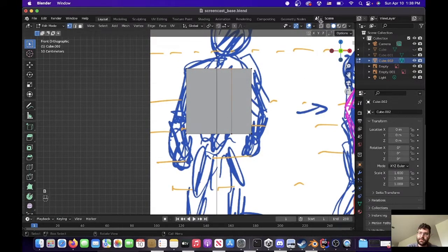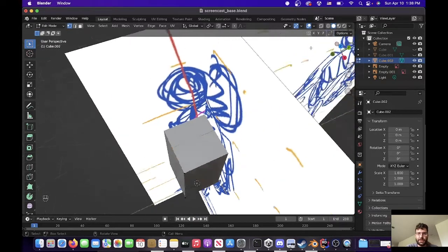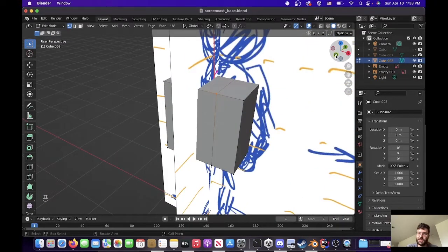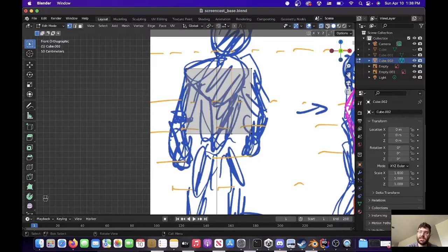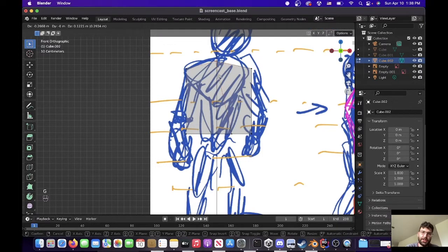Make sure again that you've got your, do I have it on? I don't have it on. Yeah, this is gonna bite me in the ass, but okay. I'm gonna leave X-ray on so that everything I do happens to the front and the back of the cube. If you hit G, so Blender is all about keystrokes, keyboard shortcuts. G stands for grab. Some people say translate, some people say move, but G stands for grab. So hit G and you can drag this, this is not the data, the vertex, and just keep dragging.